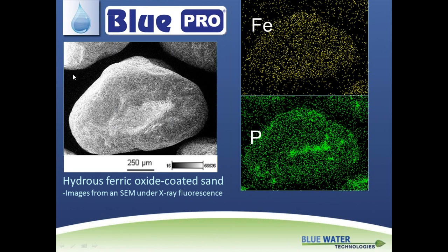And what that does is you're forming a particle that's too large to fit through the interstitial spaces of the media. And so what you're doing is you're plugging the filter. And not only is that a reliability issue, but it's not very sustainable. Those systems historically have failed quite a bit. They were always operating on the ragged edge of failure because of the methodology of removal.